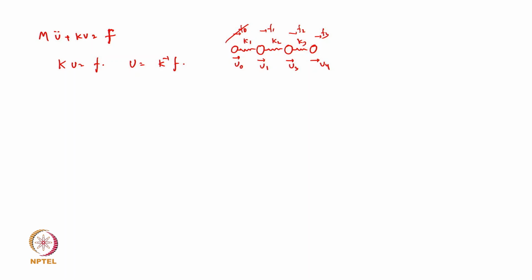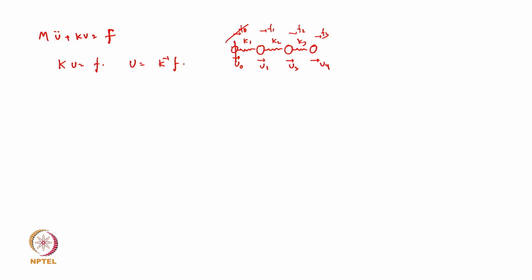And actually, that gives the infinite thing. So is that clear? The concept is clear from the physics aspect and the mathematics aspect. Very good. Now once you make this fixed, then what will happen? Then you hold it, and now they cannot go. That also reflects in your mathematics: your stiffness matrix is now no longer singular. It becomes a non-singular stiffness matrix. Therefore, you can invert that matrix and you may get the solution.